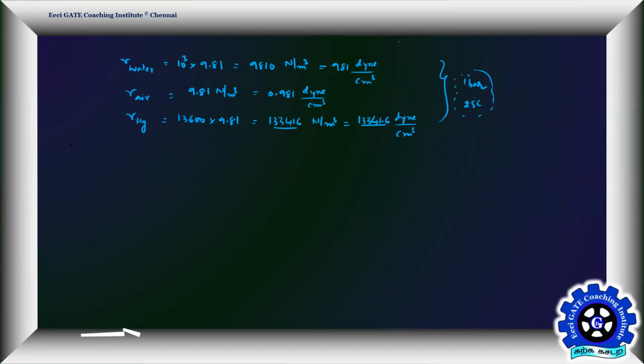The next property we are interested in is very important, which is specific volume. Whenever specific comes with a given property, we use small letters. That's just a tradition we follow. So this is volume, therefore small v. Specific means defined per unit mass. Wherever you see specific, such as specific enthalpy, specific energy, specific kinetic energy, it means per unit mass, per kg of mass, how much is the property value.